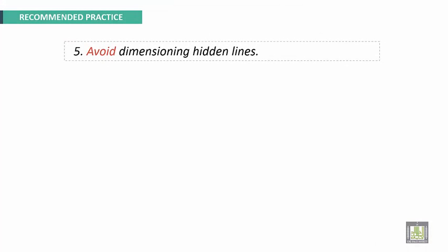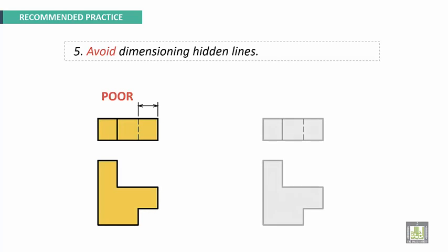Avoid dimensioning hidden lines. This should be avoided. Make the dimension on the visible line.